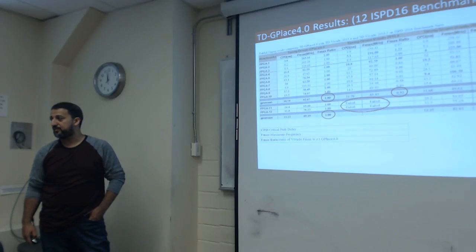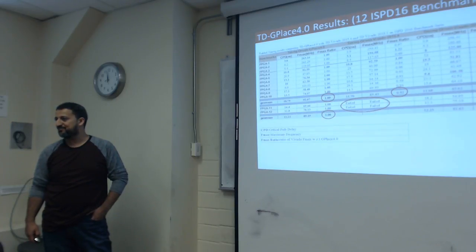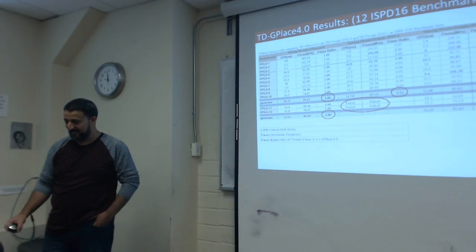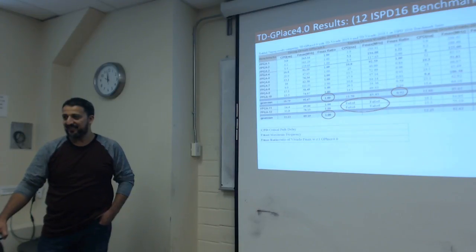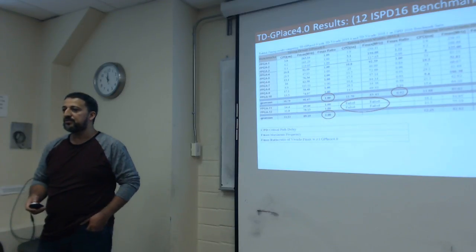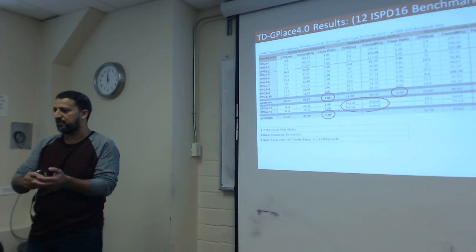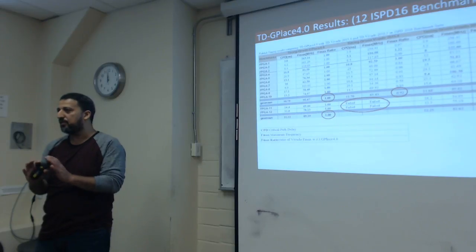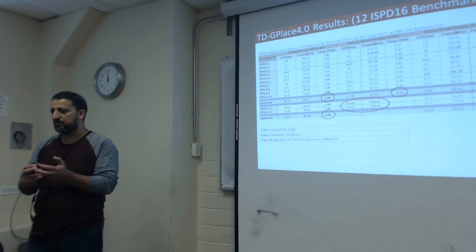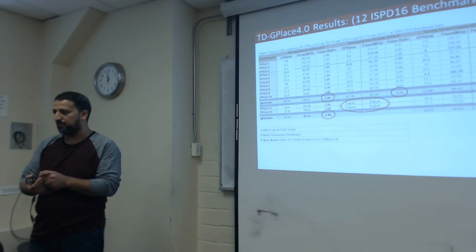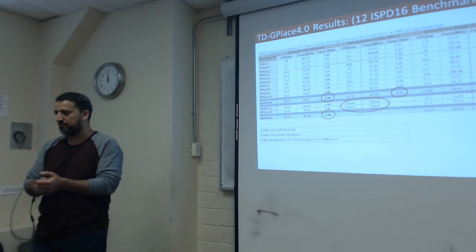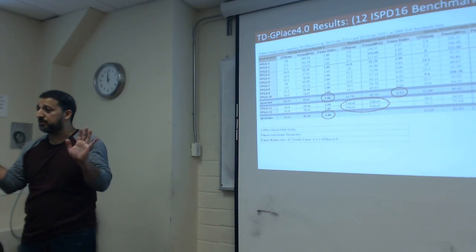Is your timing-driven version tied to match flip-flop pairs or not? Lots of these circuits are incredibly slow considering it's UltraScale and 20 nanometer; some are only running at 50 megahertz. My guess is that these are not deeply pipelined, and have long combinational paths. Also, these are the ISPD benchmarks with restricted components, and there are no carry chains and stuff like that. So only lookup tables, flip-flops, DSPs, input buffers, output buffers, load buffers. So they're still randomly generated by them.